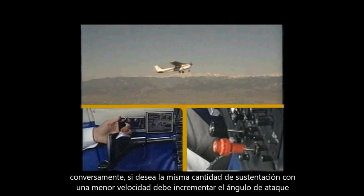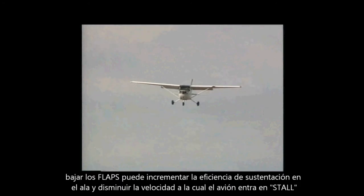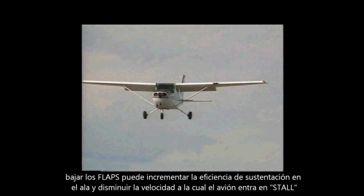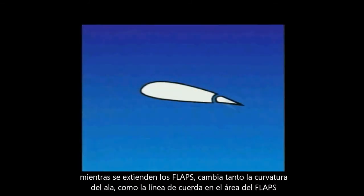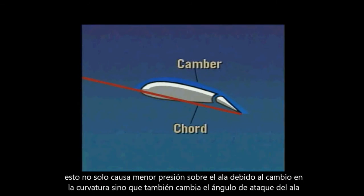Another way of controlling lift is by changing the configuration of the wing. Lowering the flaps can increase the lifting efficiency of the wing and decrease the airspeed at which the airplane stalls. As flaps extend, they change both the camber and the chord line of the wing in the area of the flaps. This not only produces lower pressure above the wing due to the change of camber, but it also changes the wing's angle of attack.